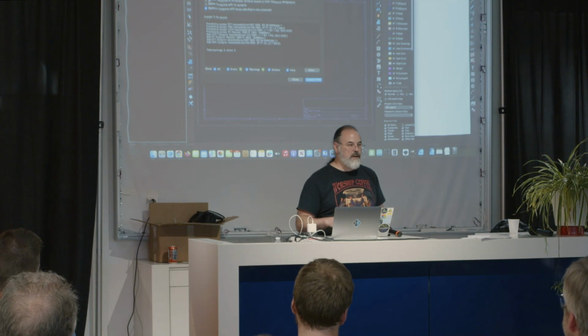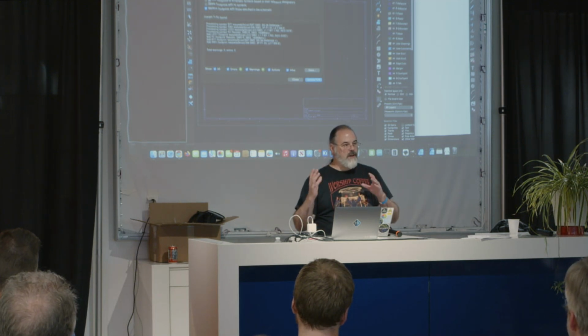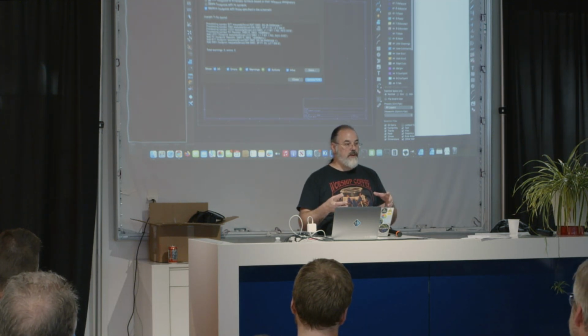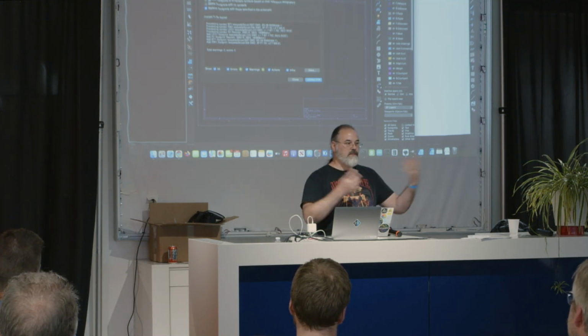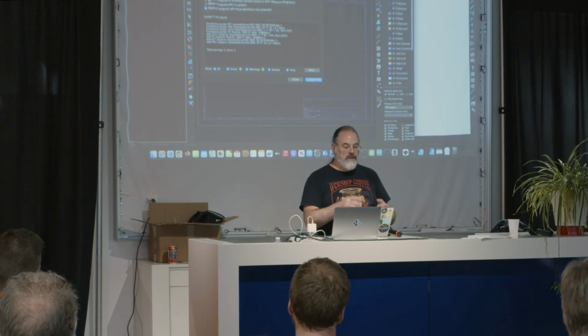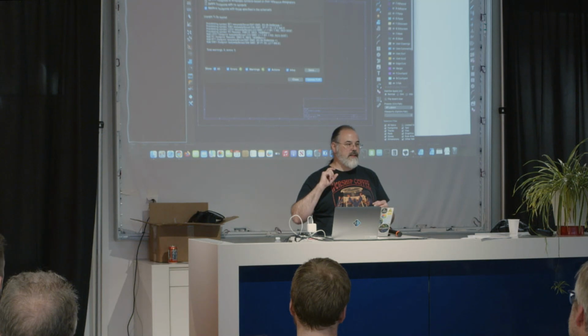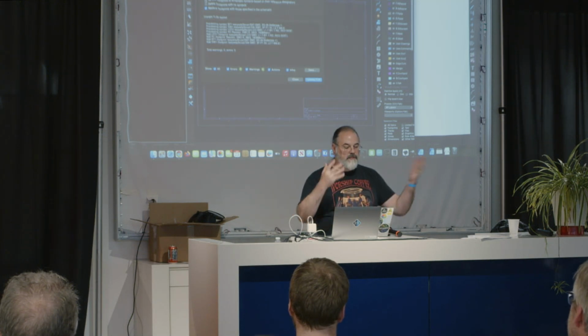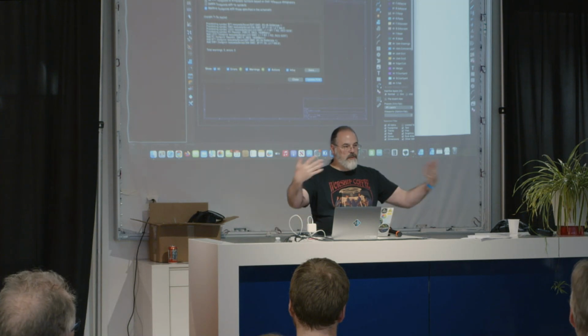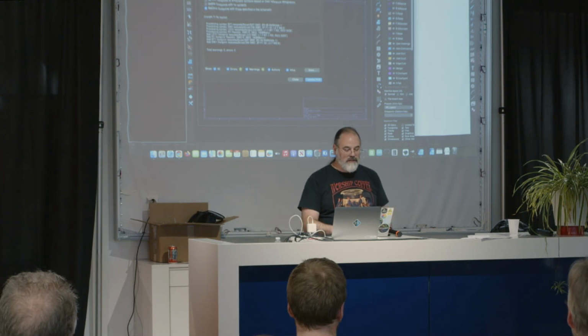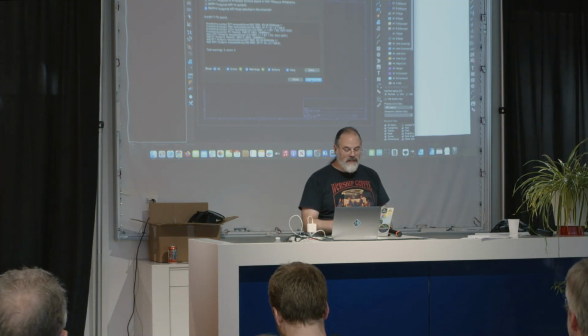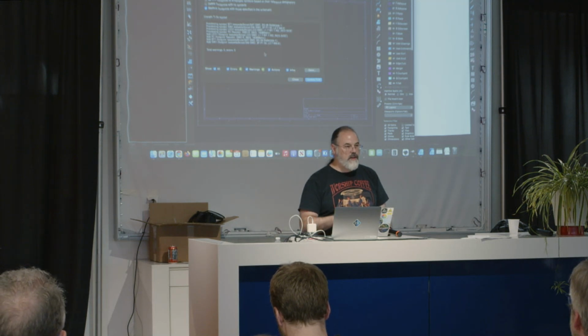It has this really cool option where by default all of the parts that you create in your schematic have a UUID, and that'll link with the exact same instance of that part. You can rename things and it follows through with that. Or you can use this relink thing. So you could delete a part completely and put back another R1 or U1 or whatever your designator was, and then say relink based on the symbol reference, and it'll relink those UUIDs. So it's actually pretty cool. It took a second for me to understand what was going on, but it's a nice, powerful tool.